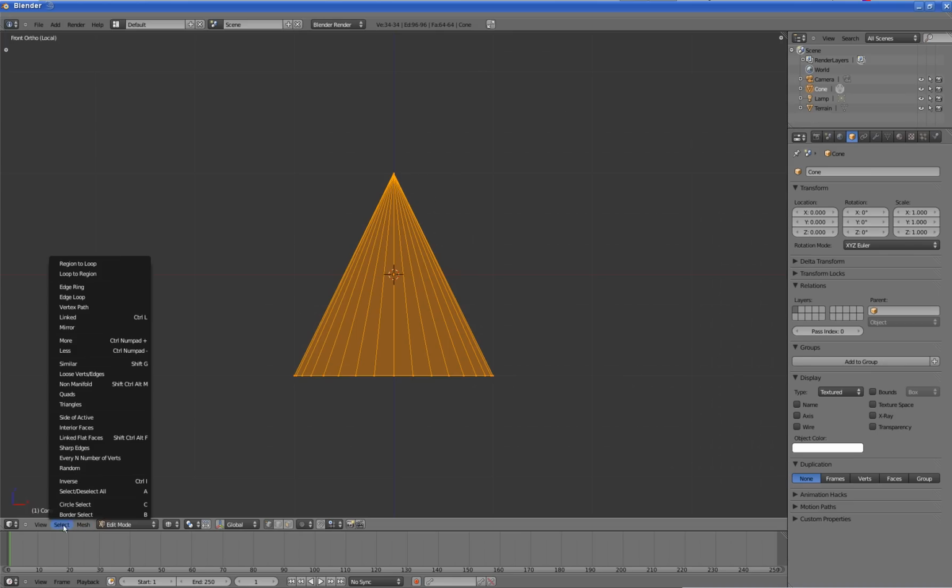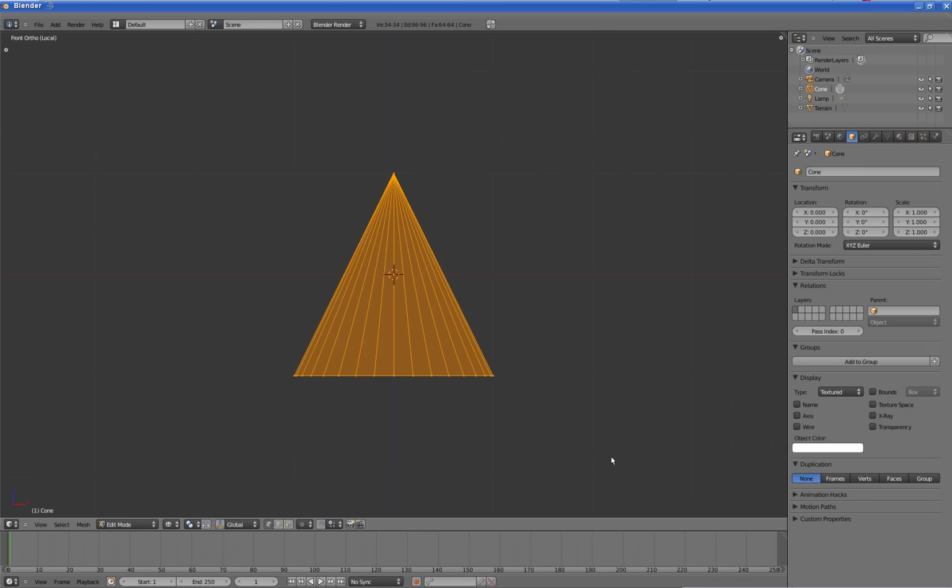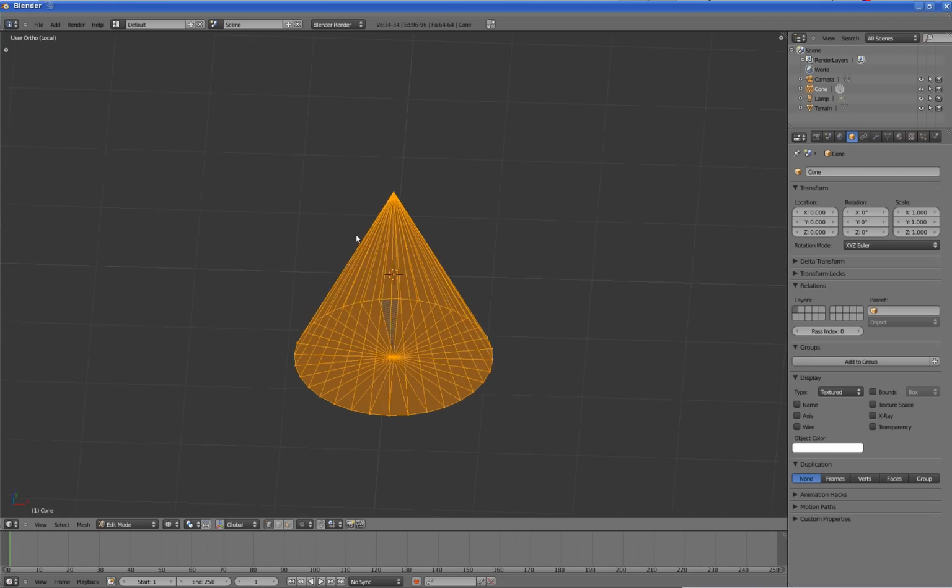In case they are not selected, I can select them in different ways. One is by pressing the B key. Pressing the B key, you can rectangle select vertices. If you are in solid mode rather than wireframe mode, the vertices that are selected are only what you are seeing. If there are vertices behind what you're seeing, then they won't be selected.